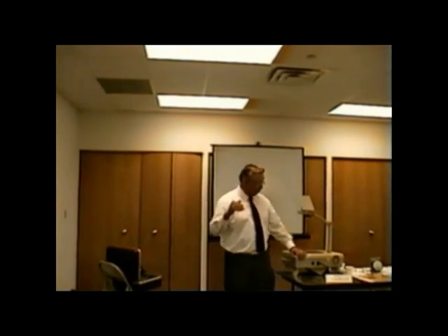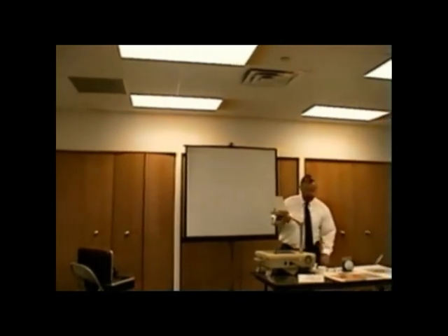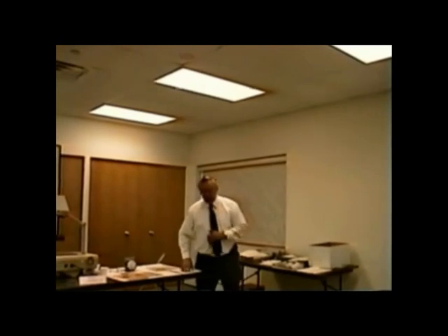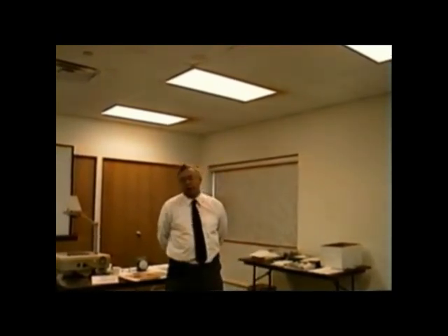Now, let me go a little bit further. We're going to ask you to take the external static pressure if you call and say you're on your third set of heat exchangers, or even second set. We're going to ask you for a temperature rise. And what you're probably going to tell us is that you can't get a temperature rise because the limit keeps opening up and the furnace keeps cycling.